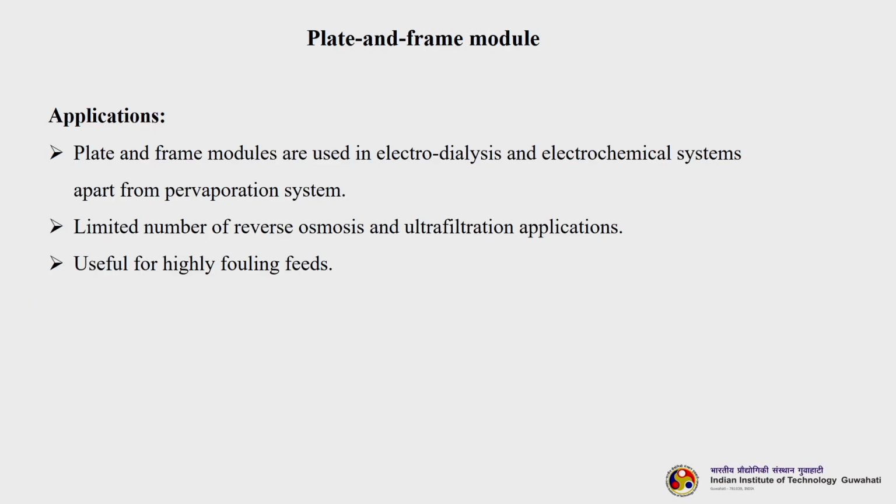The applications are that they are used in electrodialysis and electrochemical systems. Nowadays, they are also being utilized for pervaporation systems. There is a limited number of reverse osmosis and ultrafiltration applications, but another important thing I forgot to mention in the earlier slide is that they are very useful for highly fouling feeds. Sometimes the feed contains certain solutes that are highly foulable. In that case, this type of module will help us.